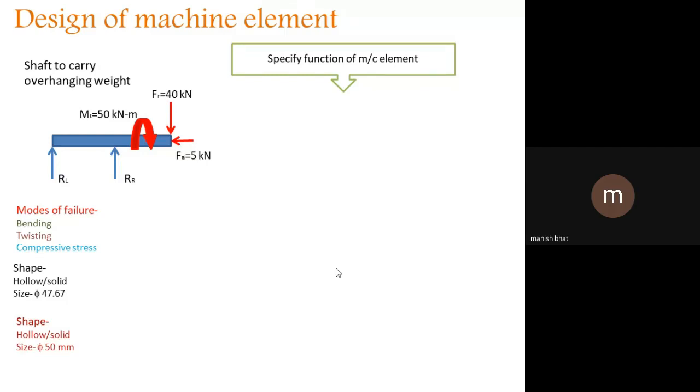Please understand well. It is the force acting, that is the weight acting at the end, multiplied by the length of that particular lever. Length multiplied by the weight which is hanging at the end. So you know that in the case of a lever loaded safety valve, some weight is hanging at the end. So the length of the lever from the valve center to that weight, multiplied by the weight, will create the force so as to shut off that valve up to 175 bar pressure.